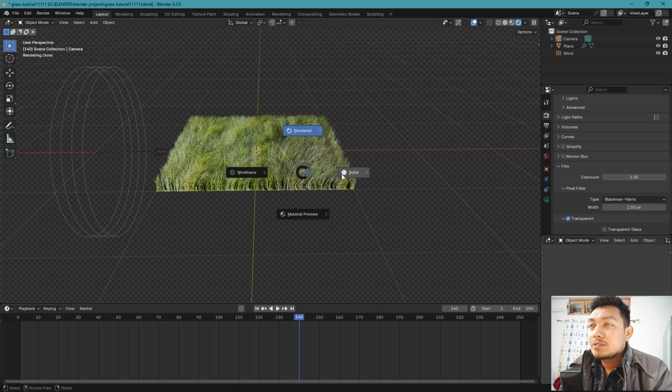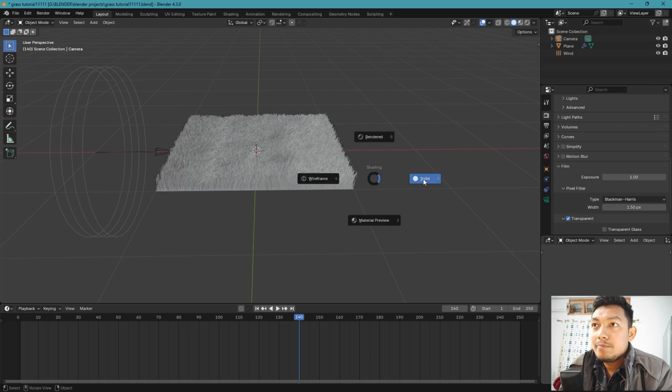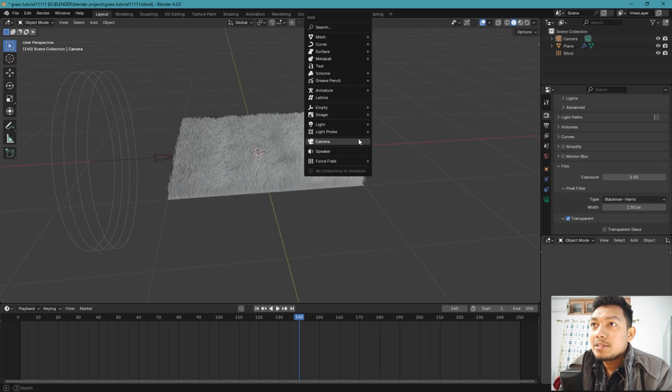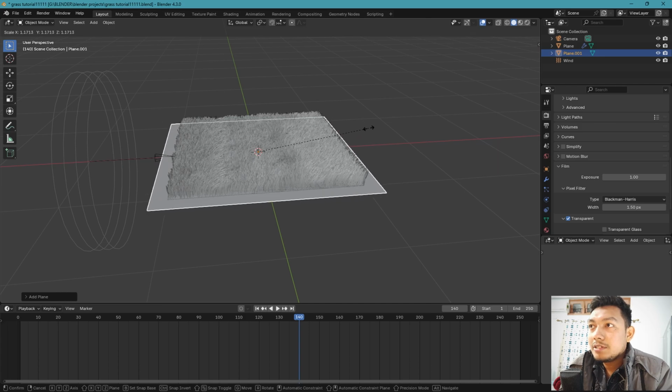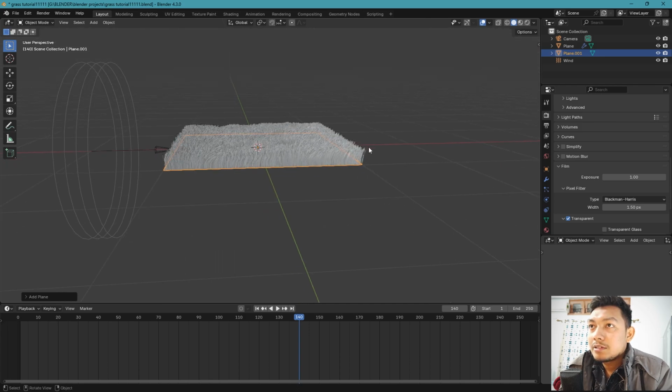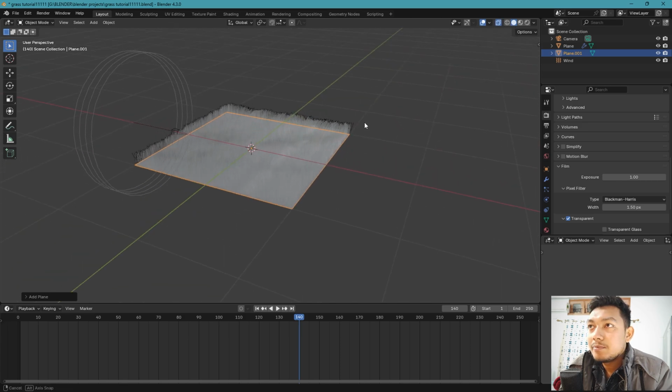So come back to solid mode. To bring this wheel, I'm pressing Z. Okay, if you get confused about which shortcuts I'm pressing, I'm pressing Z for this wheel, and for the left right I'm pressing the apostrophe key. So solid, back to solid, and let's bring a plane right now. Shift A, mesh plane, and increase. Okay, I'll go back to X-ray mode. This is the X-ray mode, and you can see the bottom.